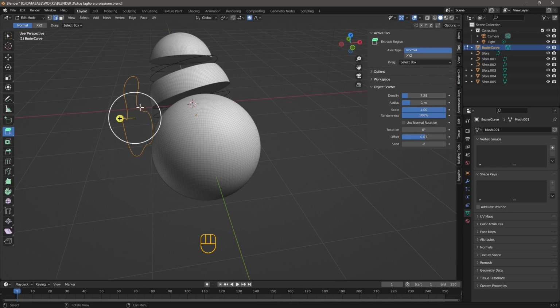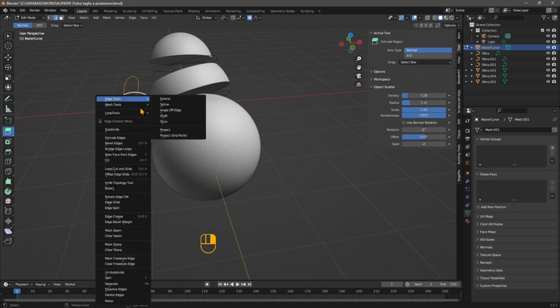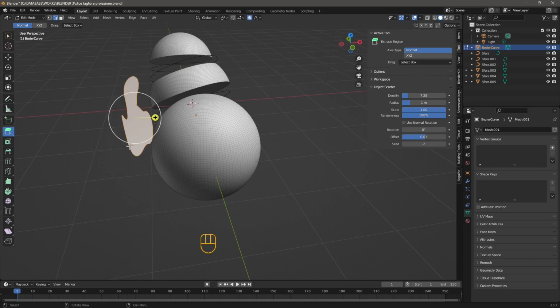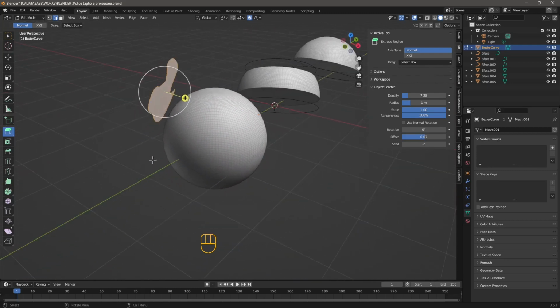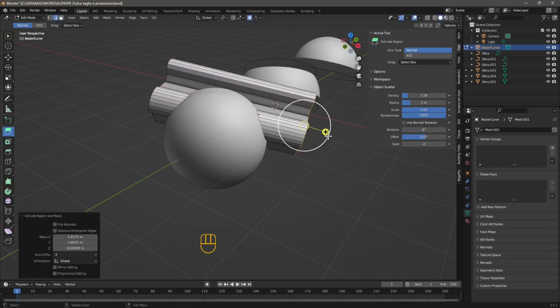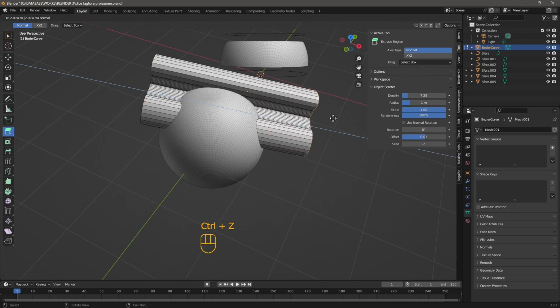And if you are having troubles with this, you can check the Blender video course, especially the first lessons. So if I now right click and do a new face from edge, it's going to create a plane. Well, a planar surface more than a plane. And then if I use extrude, I can extrude this straight like that.